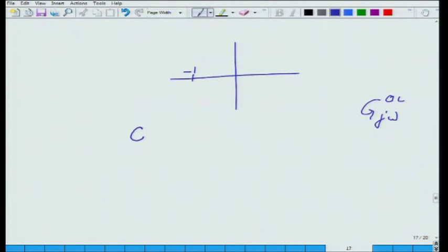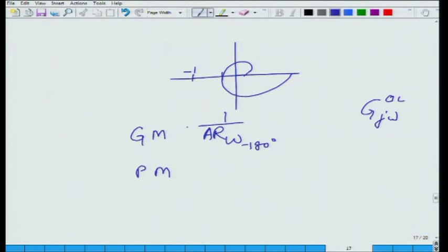If you look at textbooks, there is what is called gain margin and what is called phase margin. What is gain margin? If you look at the Nyquist plot, you can see that it is quite far away from -1, 0. If the amplitude ratio at the frequency where the phase becomes -180 degrees is a, then 1 by that is equal to the gain margin. So, let us say I am passing through -1 by 3, then my gain margin is 3.